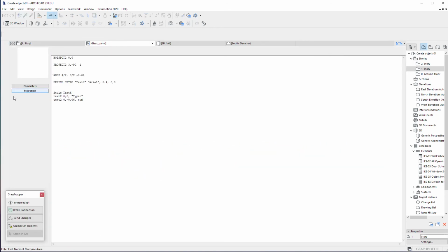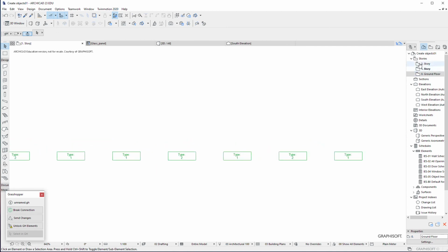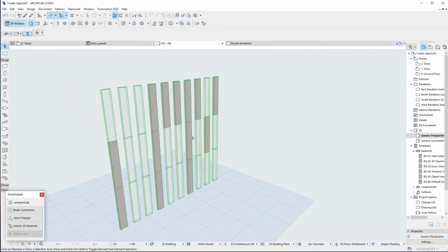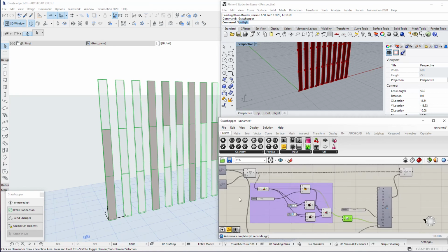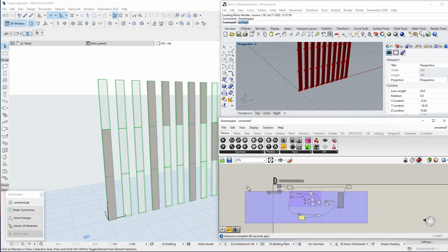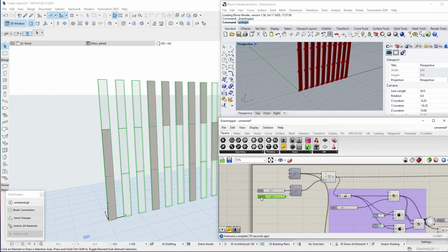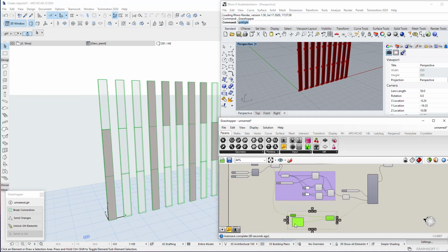Of course we can make some filament in 2D and change the color of it. We can search for that in the GDL scripting components, and we'll see how we can do it so easily. So this was an introduction to making GDL script objects in Archicad and how we can control them in Grasshopper. I find this opened many doors in the design and architecture industry, and how you can make the workspace between Grasshopper and Archicad much more useful and fast if you compare that to Dynamo and Revit.